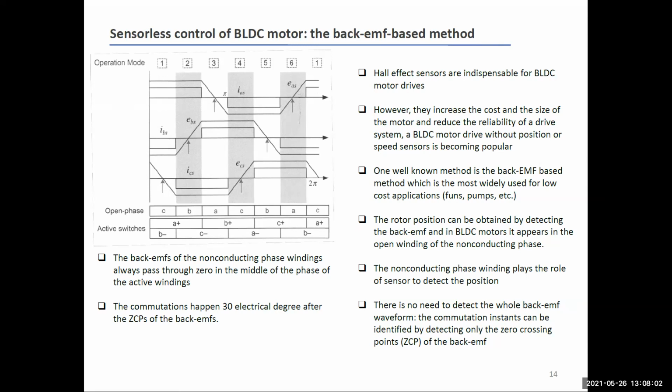Basically, there are a lot of different methods, okay? But one well-known method is called the back EMF based method, which is described here. So this method looks in detail at the back EMF evolution in time, okay? And specifically, what is under evaluation is the back EMF of the phase which is not energized.